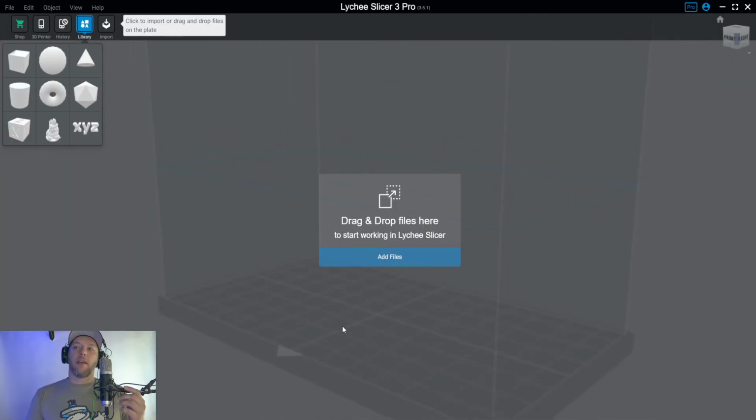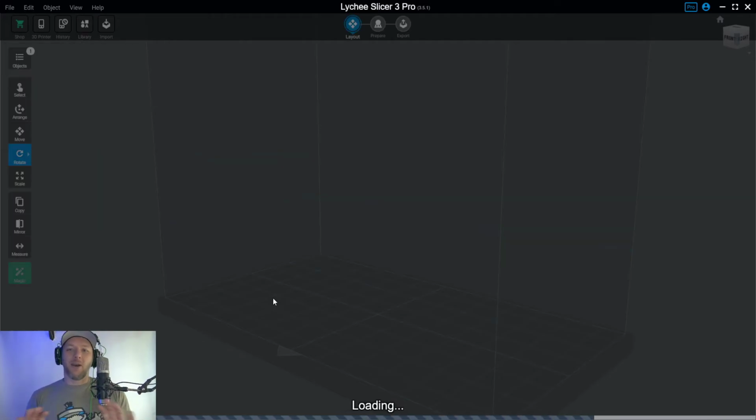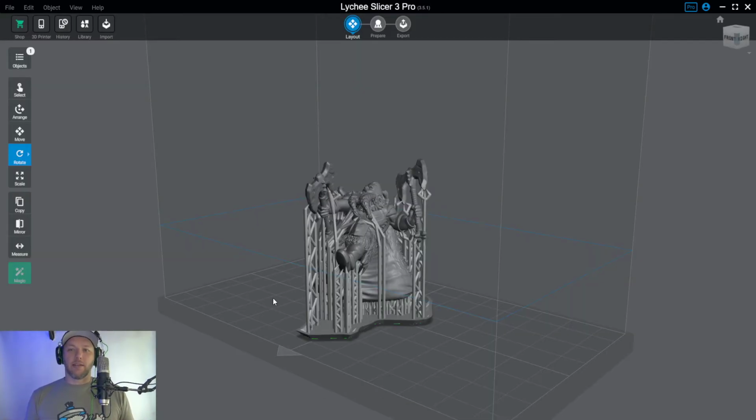Like all failures, and this is cliche, guys. I know it. I totally know it's cliche, but all failures are just lessons, especially when it comes to 3D printing, right? If you print and you have a flat spot in a place where you placed a support, you just learned something. What you learned is that that one support wasn't enough. And that's easy to fix. It sucks because you have to print again. You might put more time on the printer. You might have a deadline, or you wanna have it ready by Saturday. But it's the name of the game. Don't let it frustrate you. Fix it. Learn from it.